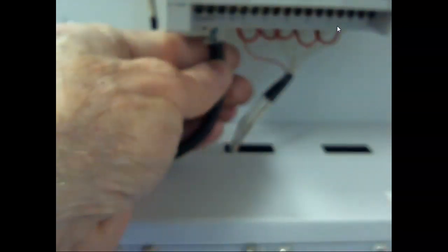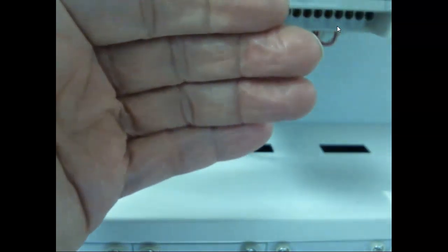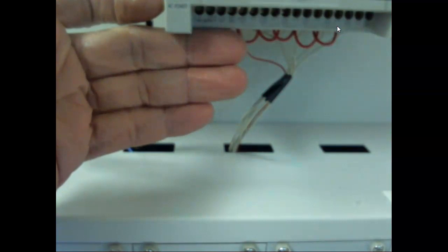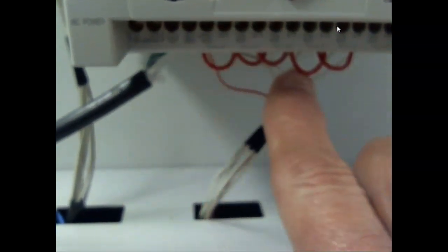It's got a built-in DC power supply. We call this an AC/DC relay PLC. It's got its built-in power supply, so it hooks up directly to Alabama Power. Or here we've got TVA, if I can get it to focus. No, can't. So they call it L1, L2, and then these are the commons here. We'll talk about how we wire this thing up. So the problem is one of my commons popped out.